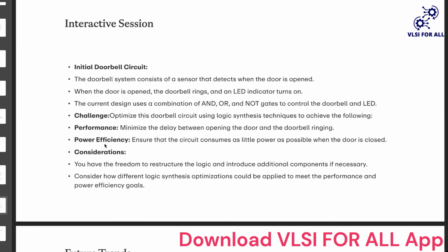Like I'll try to explain. I mean, if you guys can't think through, I'll try to explain how you improve the performance. In this case, changing the logic structure, the way you use the AND, OR, and NOT gates to design, so that itself can be optimized. Rather than using a sequential logic to capture the data and only in the next clock cycle enabling the data, I can use a parallel logic to reduce the delay. Instead of sequential, I'll just use a parallel logic. Parallelly, I'll keep sending the data.